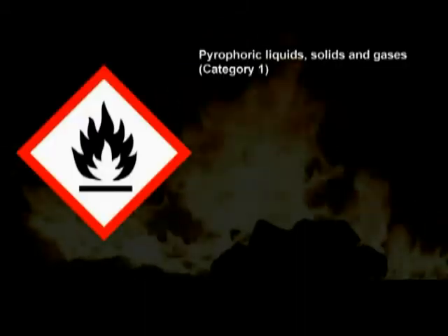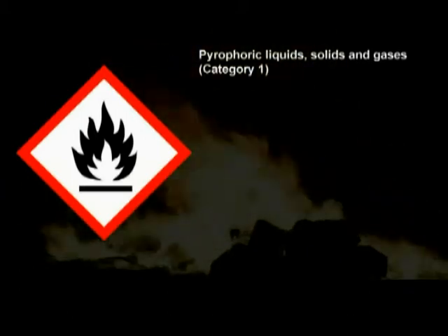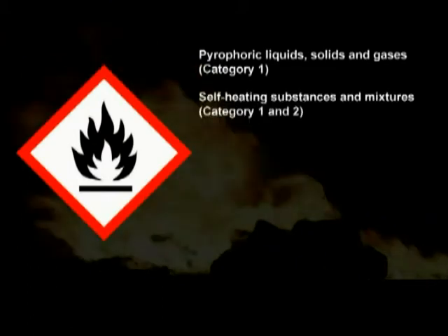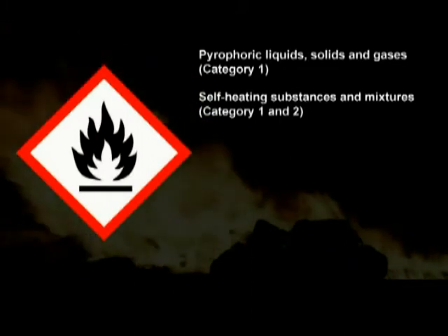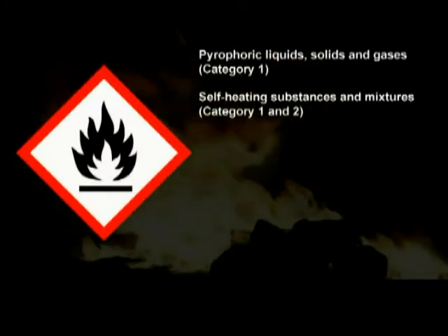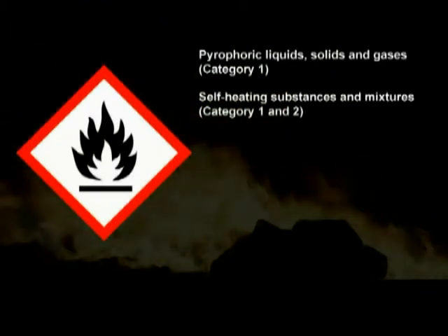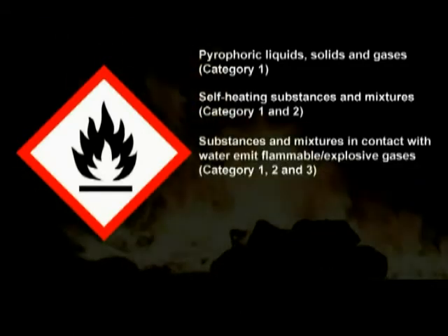Pyrophoric liquids, solids, and gases, Category 1. These products can catch fire very quickly, spontaneously, if exposed to air. Self-heating substances and mixtures, Category 1 and 2. The products may catch fire if exposed to air. They differ from pyrophoric liquids or solids in that they will ignite only after a longer period of time or when in large amounts.